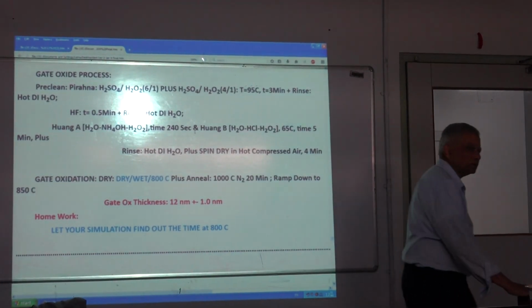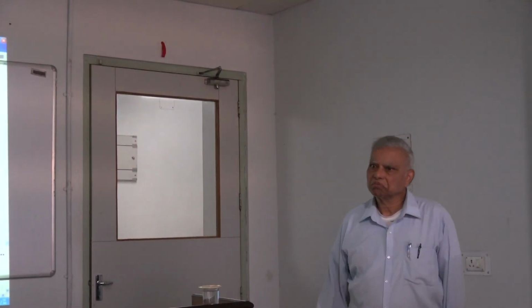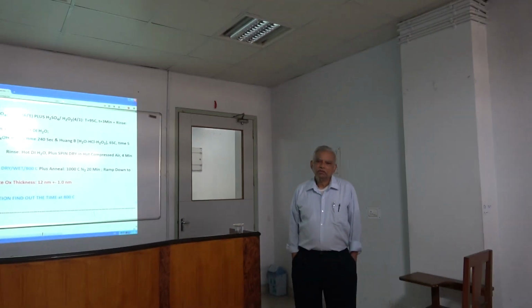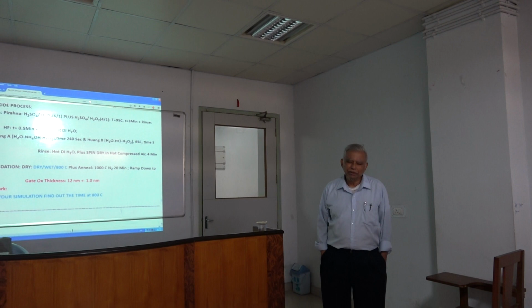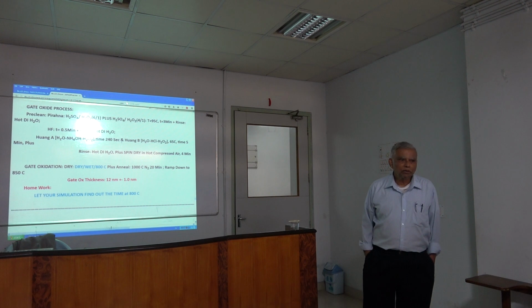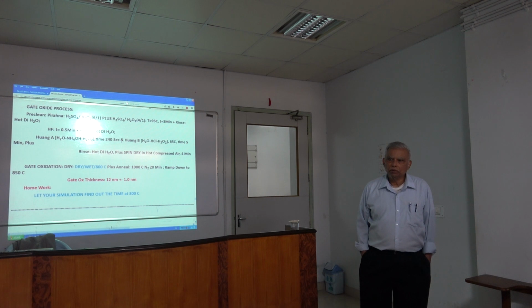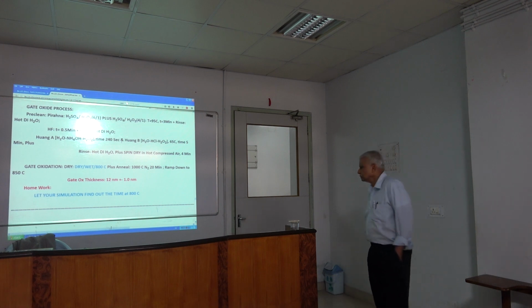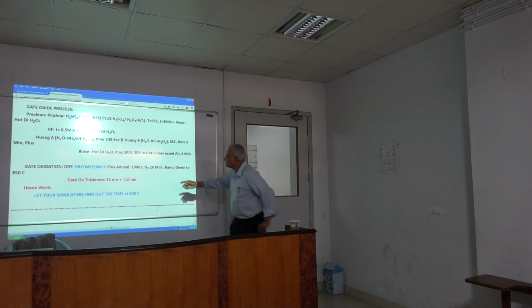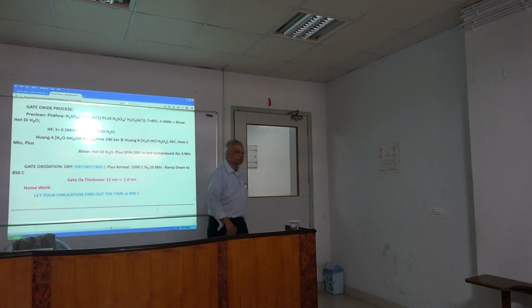Prior to that, the gate oxide thickness was in the realm of 300 angstrom, 30 nanometer range. The 1 micron technology, which is the end of VLSI, used about 30 nanometer of EOT, the gate oxide thickness, although it's not exactly oxide. But we went down to this level to make ULSI happen.